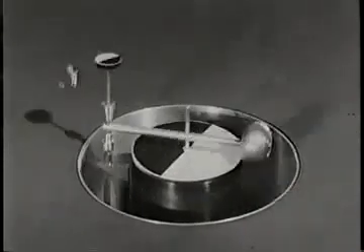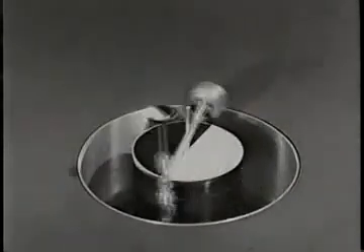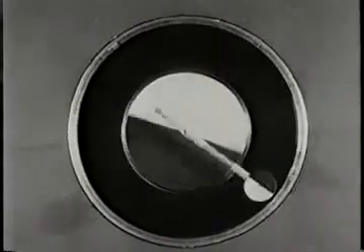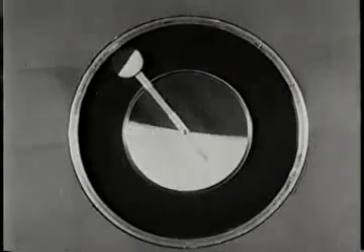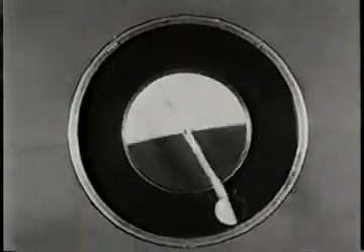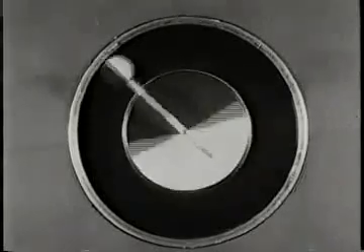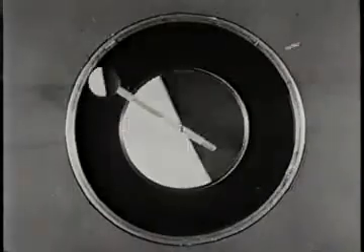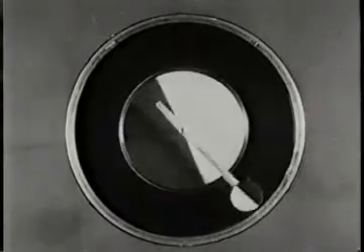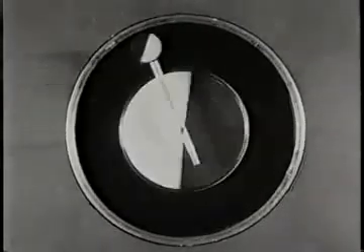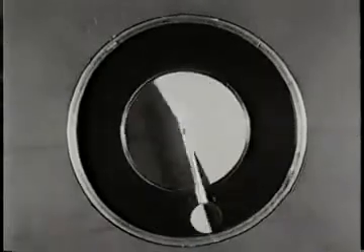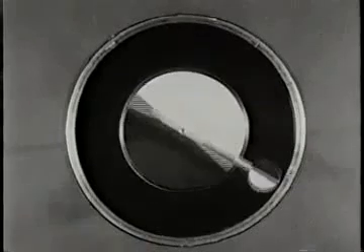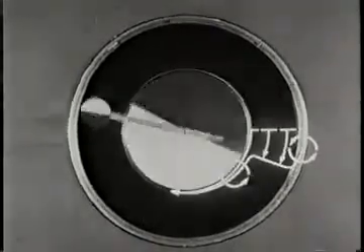In the flow without the field, the vorticity is such as would cause a loop in the fluid to link a changing flux when the field comes on. So J cross B changes the vorticity to avoid this. As we repeat the experiment, observe the direction of the vorticity. With no field, it's anti-clockwise. The field makes it clockwise. The J cross B forces have also produced intense anti-clockwise vorticity in the thin Hartmann layers. So here, J cross B has rearranged the total vorticity, not suppressed it.